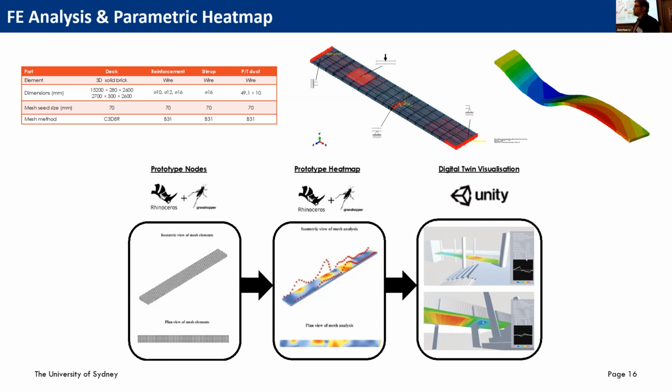That penetration tells us whether corrosion is about to happen or has already happened, and based on that we can make a decision to inspect the bridge and do the remediation on the bridge. So it's not measuring the corrosion itself. Okay, thank you, Ali, and thank you.